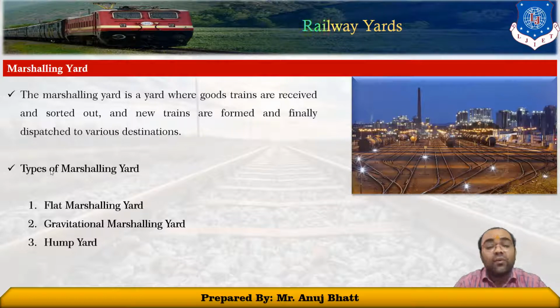However, the recommended gradients for a particular yard are decided after a test run of the trains over the humps. Also, taking into consideration the rolling quality of different types of wagons, the spacing between successive groups of wagons is noted. While the topography of such hump yards plays an important role in deciding the amount of gradient that is provided.